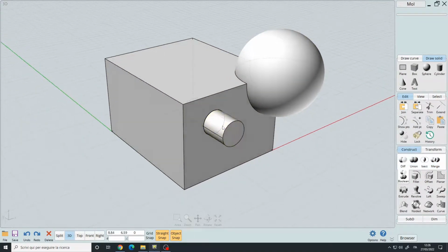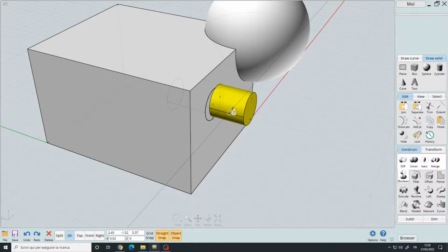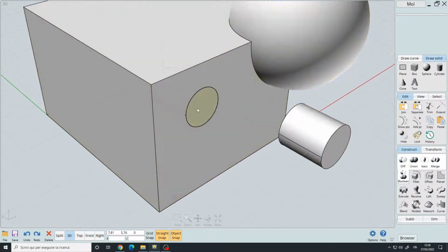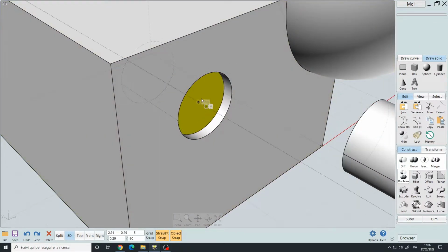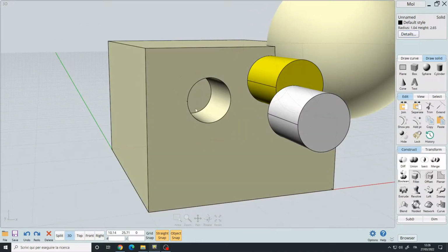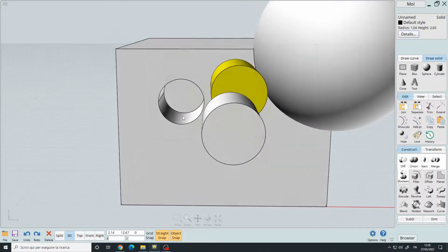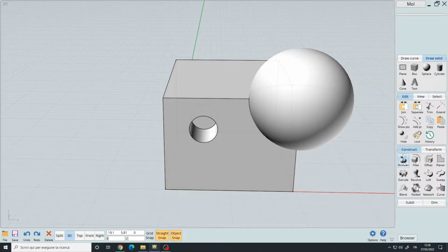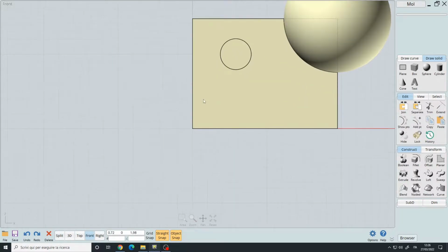Select objects to merge these two. Done. And now I can still move the cylinder out of my way, but I will retain this inner part for further operations. Like maybe I want some kind of bolt. I can move it here, or I can simply move it out of the way and I have the difference operation. You can also perform Boolean operation using curves.